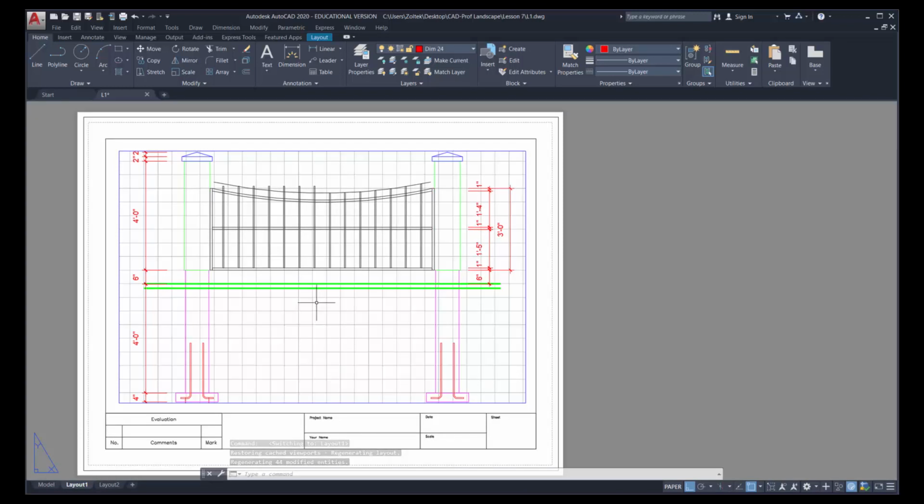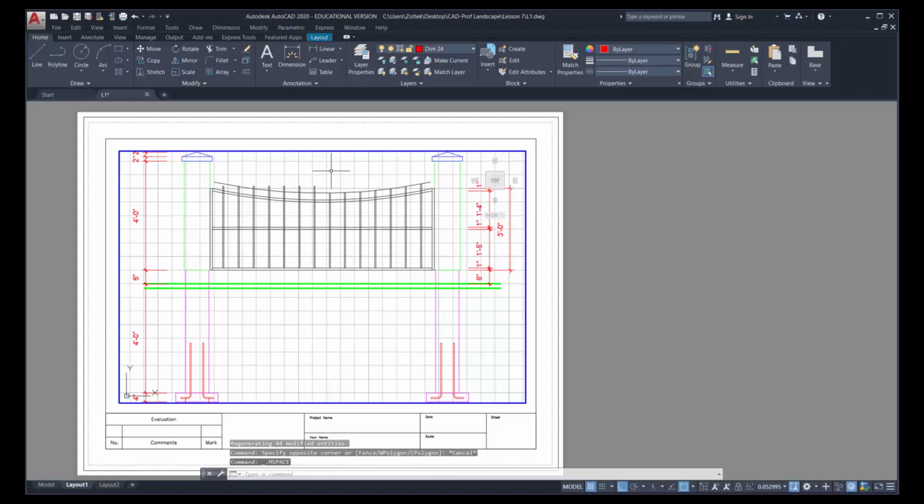Now in order for us to actually have this at the right scale, remember this drawing is a 1/2 inch scale. According to the information I provided to you earlier, a 1/2 inch scale is 1:24. So this is how we set up the drawing. I'm going to double click inside this viewport, and you'll notice that the viewport layer will become bolded. I'm going to type in the letter Z and enter. You'll notice on my cursor it says scale factor NX or NXP.